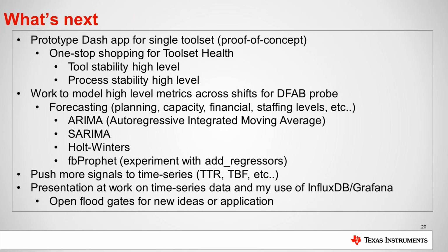Now, as far as normalizing, we normalize in our fab on our cost using photo patterns. As far as on a tool basis for, say, a fail event, we're looking at how many wafers we actually move through a specific tool at a given time. We typically normalize to 10,000 wafer moves through a tool and use that to look at our fail events.